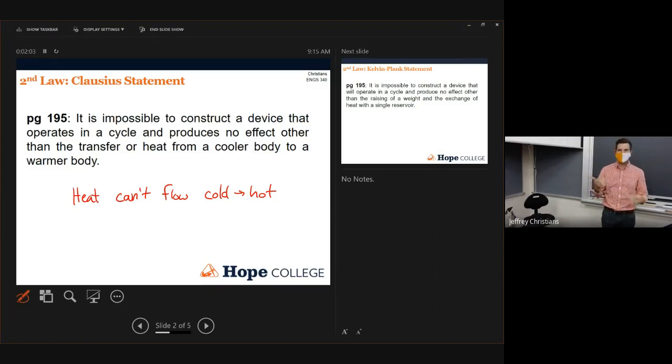There's no way that's possible. And I agreed, and the second law agreed. We calculated what the change in entropy was. The change in entropy was negative. And I said, really what happened is we broke the second law, which is kind of this: heat can't flow from cold to hot. But thinking about what's actually happening in that process, steam coming in and liquid water coming out, it's not clear that we broke that. At least it's not clear to me. They're a little bit different.